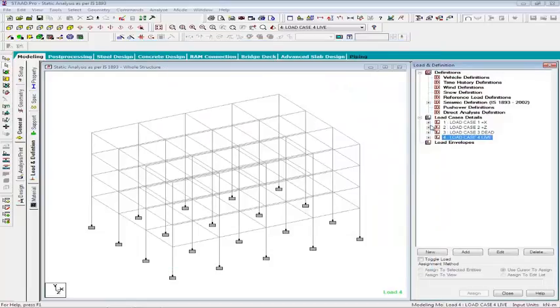Before moving to auto load combinations, we have to define the analysis and print data command between loading case 1 and 2 and loading case 2 and 3. This will help STAAD.Pro to calculate loads for load case 1 in X direction and load case 2 in Z direction before doing the combinations.